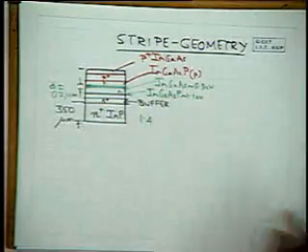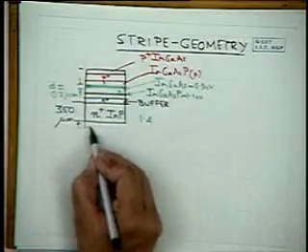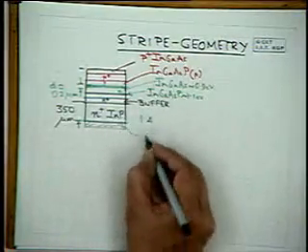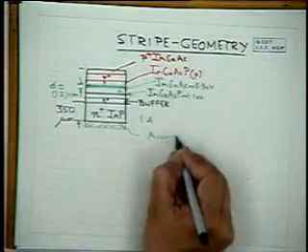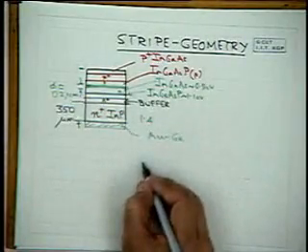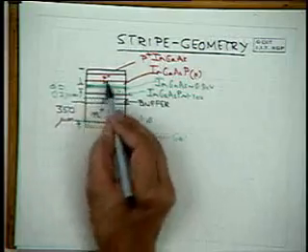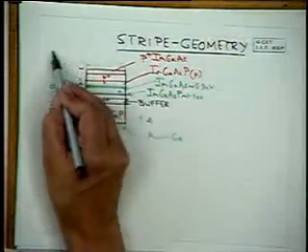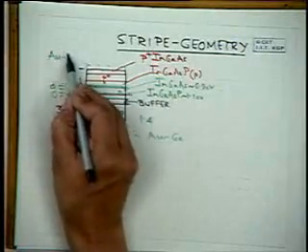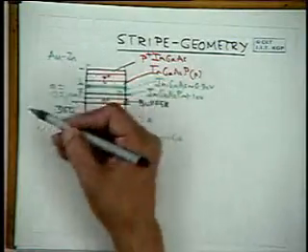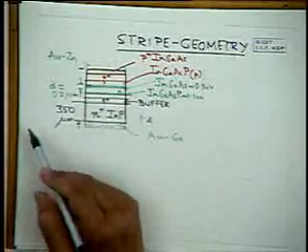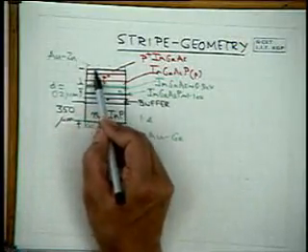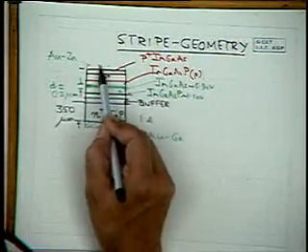You just evaporate ohmic contact. Okay, on N plus indium phosphide, the ohmic contact would be typically gold germanium alloy. On P-type, it will be gold zinc. Or you can have multi-layer. I'm describing the simplest. This is an alloy. Zinc is a P-type impurity, so it diffuses and gives you a low resistance contact here.